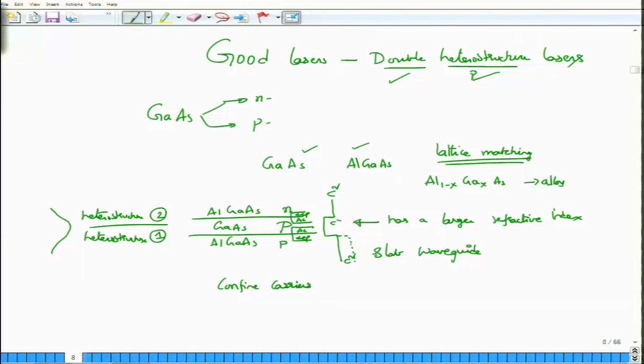Okay. What is interesting is that as the optical mode propagates through this active layer, it is actually seeing the accumulation layer. When we say accumulation layer, it means that more electrons are to be found in the conduction band, and similarly holes are to be found in the valence band in the central region. And because there is a large number of electrons, it is possible for us to employ these electrons and corresponding holes to make them recombine, band to band recombination, so that they can give off nicely a large number of photons.